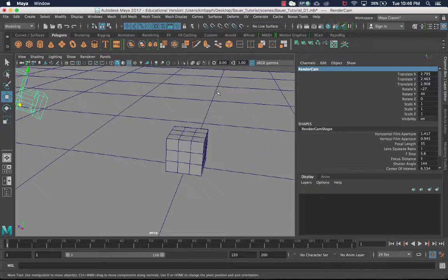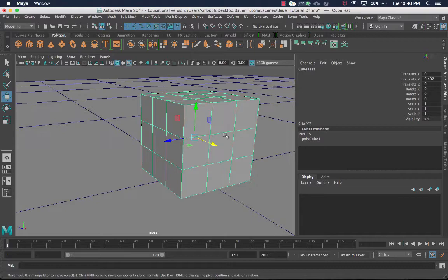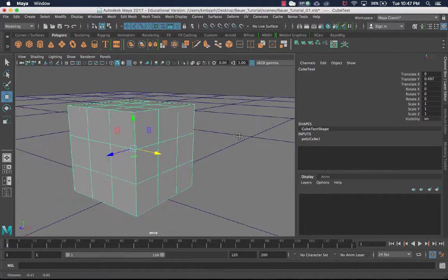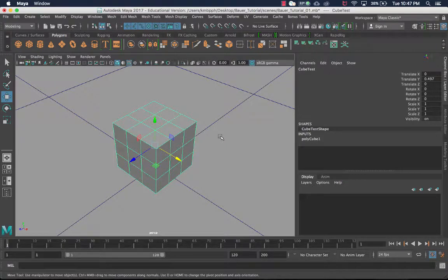Okay. So the next thing that we want to talk about is just how to set up some planar mapping. So we are going to set up UV maps on our cube. A UV map is really like an onion skin that wraps around your object. And what it does is it's a way for us to kind of paint textures on. So if you were to think of like a t-shirt that you're wearing, it kind of sits on top of your skin. It sits on top of you, which would be our object if we were thinking in Maya terms.